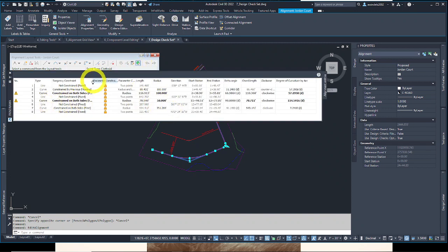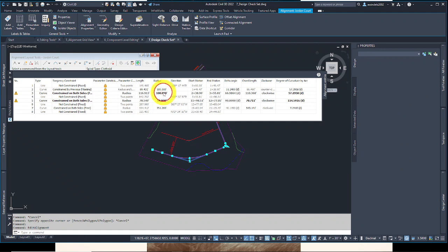And it's saying also it shows the warnings in here, which is helpful. Subdivision curve, probably too small. And it also bolds them, the radius where it's the degree of curvature, it's not long enough or big enough radius size. So that's probably telling us where the errors are. These are the items that have violations. So that's where the very specific values are that are causing these violations. So item 3, we'll just type in a new radius here.